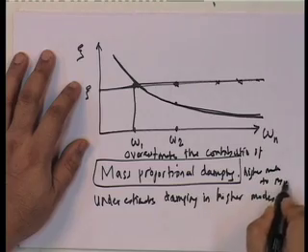Understand that if you underestimate damping, what are you doing? Lower damping always increases the response, except, remember, in transmissibility, where actually you want damping. But let us not go there, that is a design.